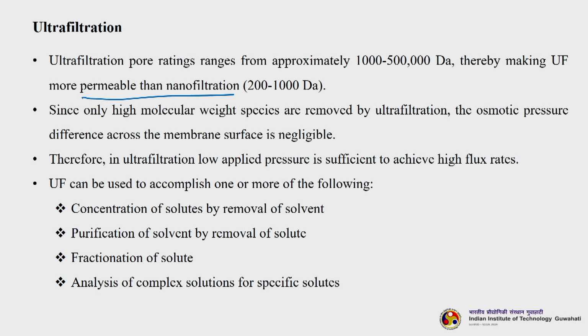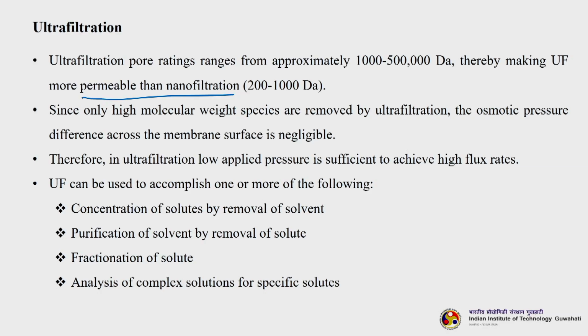Therefore, in ultrafiltration the applied pressure required is lower than RO to achieve high flux rates, and ultrafiltration can be used to accomplish one or more of the following objectives. Either you can target a concentration of solutes thereby removing the solvent, or you can have a purification of solvent by removal of solute, and fractionation of solute. So, we have binary fractionation, we have tertiary fractionation. And also analysis of complex solutions for specific solutes.